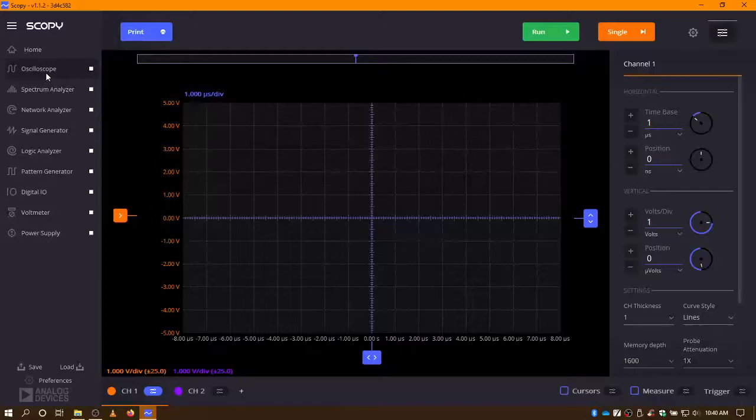So that's the usual rule of thumb to use for any kind of oscilloscope. When you see that bandwidth number on an oscilloscope, take about a third of that as a good input signal. Over that, you're going to see some signal degradation. So that's the rule of thumb to keep in the back of your mind.